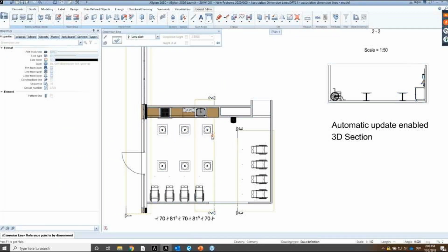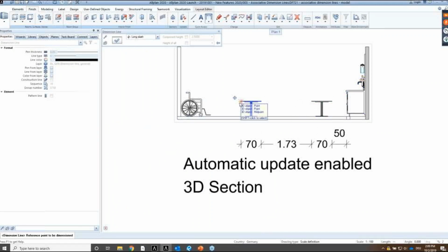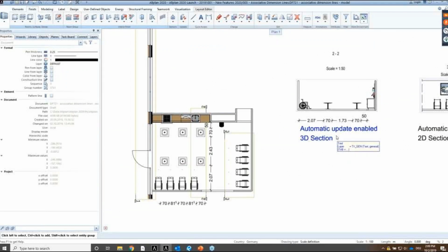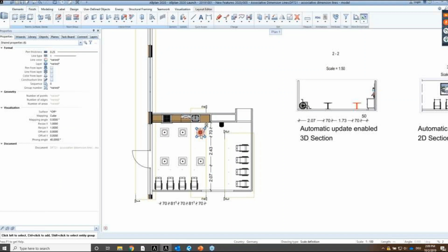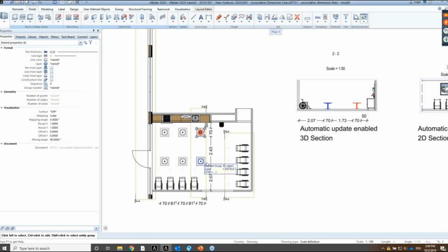You see here we can just make some architectural dimensioning, like the position of furniture, and as always somebody will change their mind, and they will get updated. So even if this is just a proof of concept, we can now make the dimensioning in other windows as well. And now when we start making modifications, this can be done with all plans closed. You don't need to know where the plans are, because you are moving the physical position of an item, and the dimension line is just following the points that belong to that item.